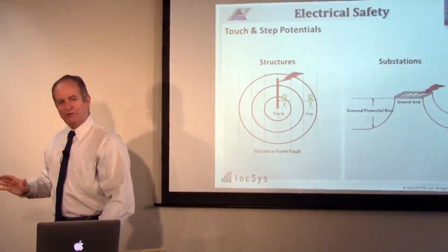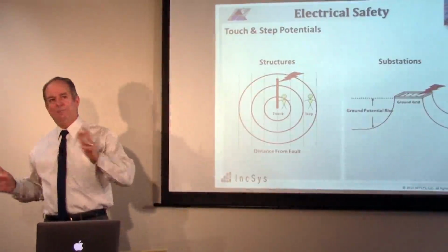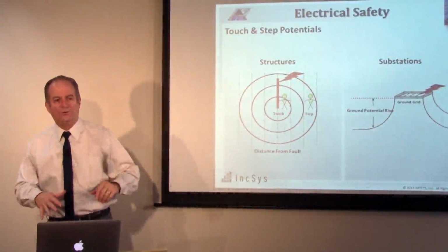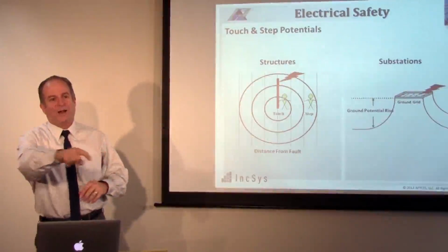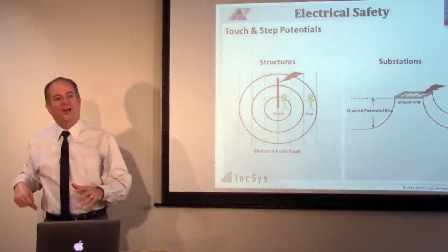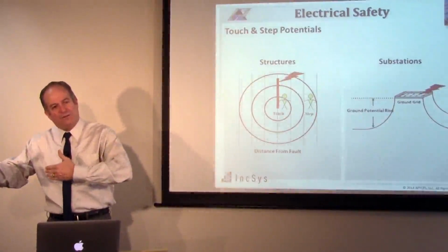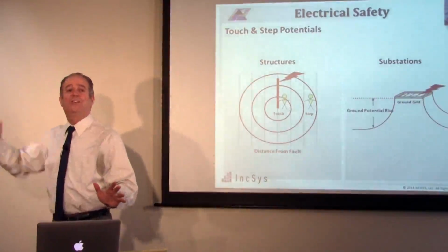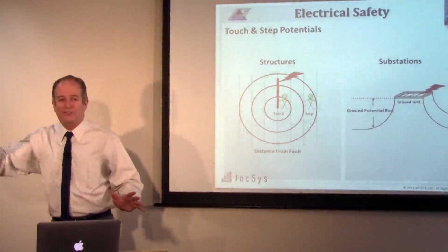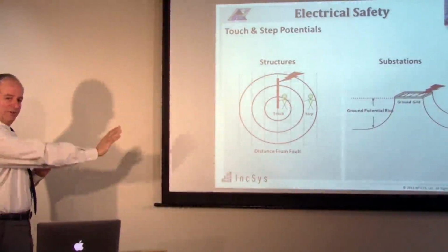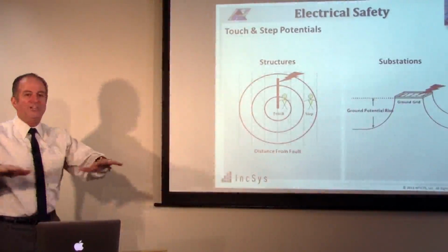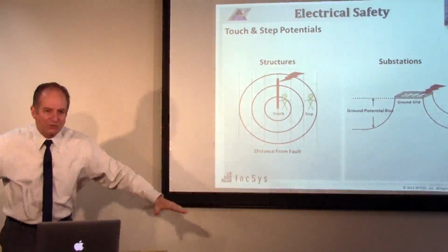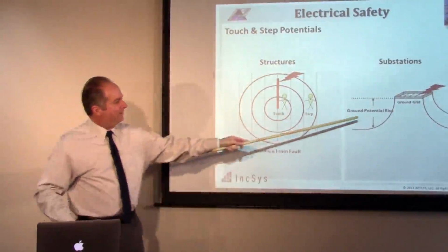So most substations, all your modern substations, maybe dating back 20, 25 years, normally put a ground wire around the outside of the fence, 3 feet out, a meter out, tied into the ground grid, so a person standing outside the fence could be touching the fence just as if they were inside standing on the ground grid touching the fence. So there's this equal potential zone around. But once you get away from that, the potential drops. So here it's dropping, okay?